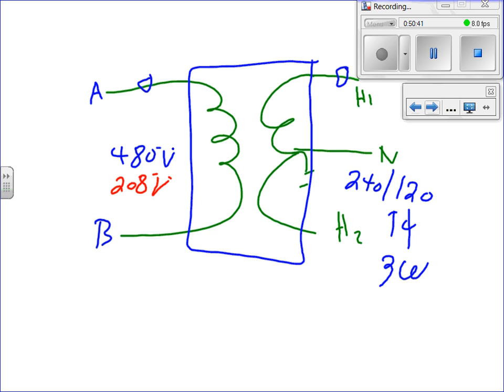The same thing, guys. Between two phases, phase A or B. Does it have to be A and B? Can it be B and C? No problem. Any two phases. The system that I'm having here is right in here. I'm just tapping any of these two phases. Here's my phase A, phase B, and phase C. That's a system, and I'm tapping from any of these two phases. The other one could also be 600 volt.